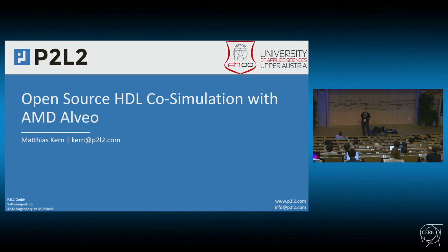Last one. There is a question from Discord. It's similar to the question that has been asked previously on the clock frequency. But I think the main question is whether you apply some special constraint, you run the design under test with a lower clock frequency to meet timing on the Alveo, or you keep the same frequency that the design is supposed to run at?